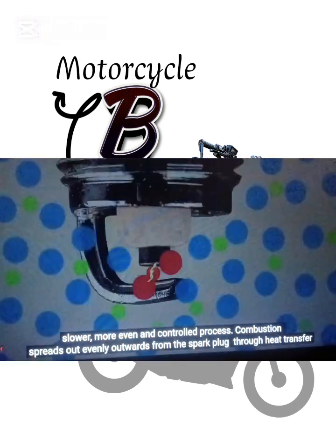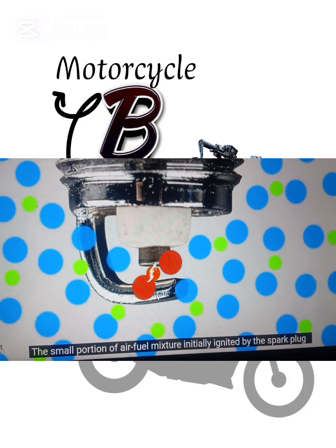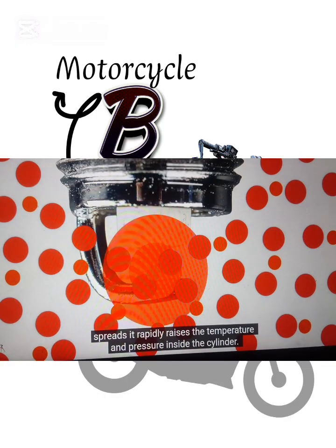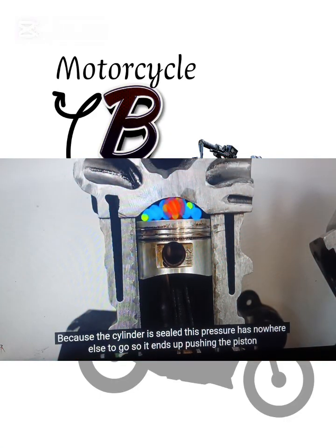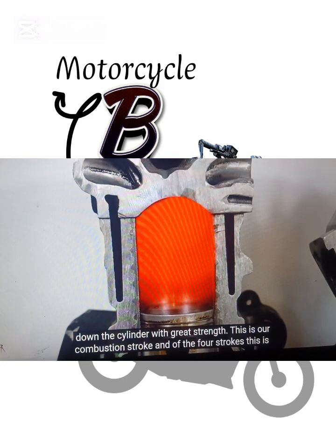Combustion spreads out evenly outward from the spark plug through heat transfer. The small portion of air-fuel mixture initially ignited by the spark plug heats up and ignites the next layer of the air-fuel mixture. This layer then ignites the next layer, and the process continues until all of the air-fuel mixture is burned. As the combustion flame front spreads, it rapidly raises the temperature and pressure inside the cylinder. Because the cylinder is sealed, this pressure has nowhere else to go, so it ends up pushing the piston down the cylinder with great strength.